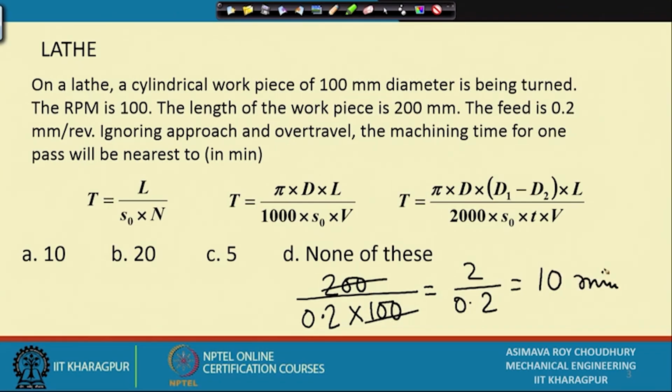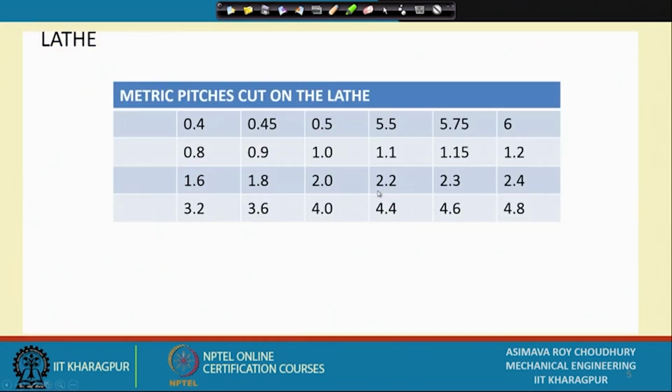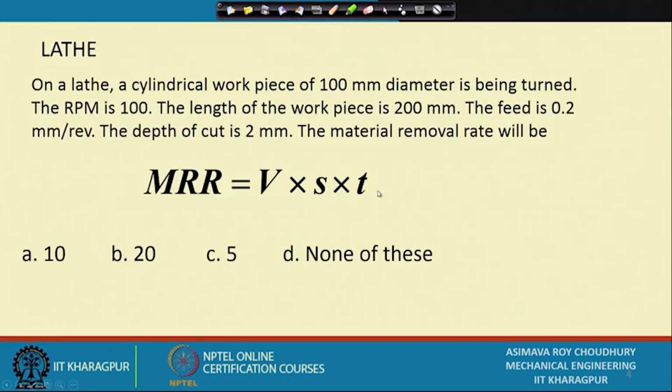Okay. So, on a lathe, a cylindrical workpiece of 100 millimeters diameter is being turned. The RPM is 100, the length of the workpiece is 200 millimeters, the feed is 0.2 millimeters per revolution, the depth of cut is 2 millimeters. The material removal rate will be? Now, material removal rate is given by...